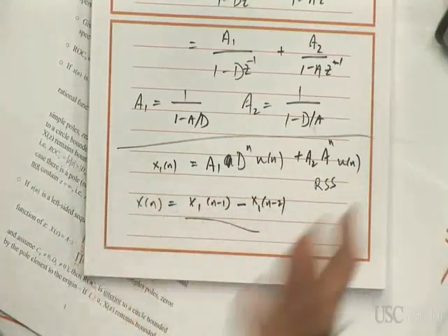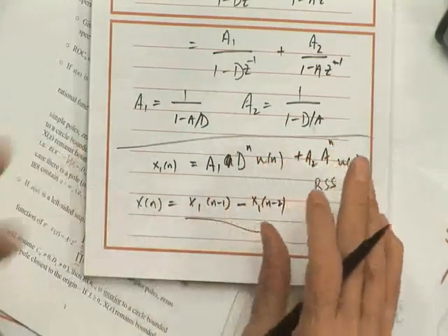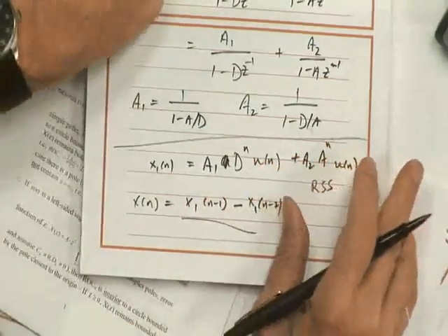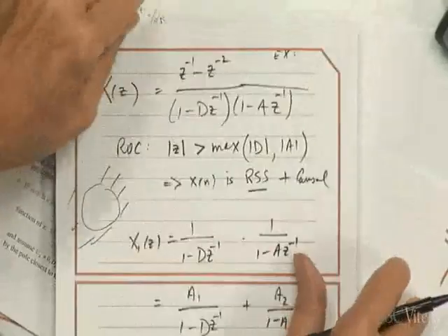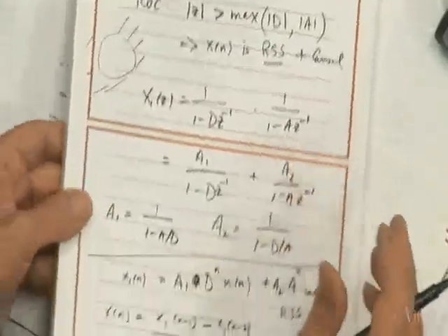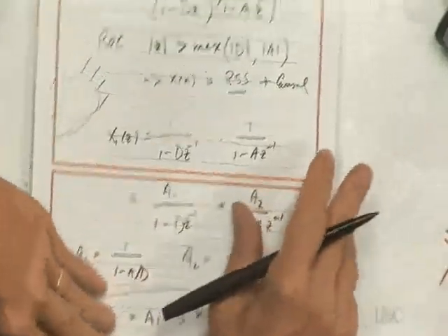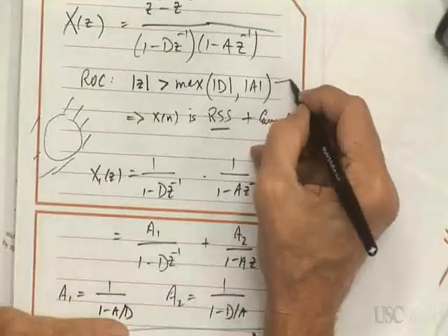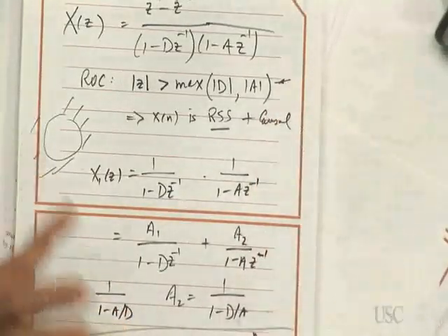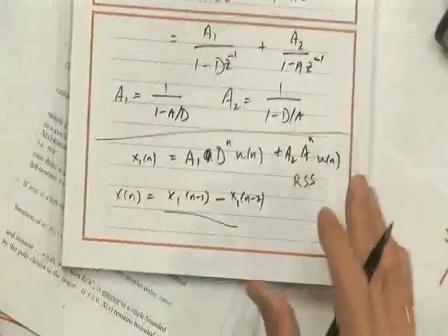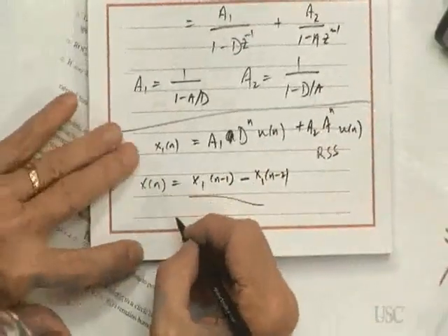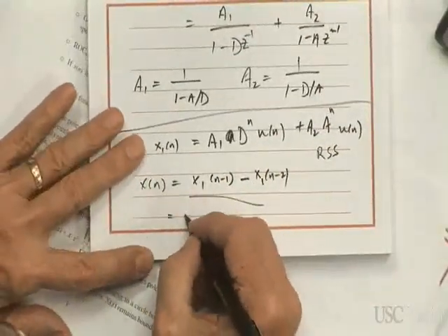So take a look at this example. I find that a nice way of doing inverse Z transforms that have powers in the numerator. It's a simple way to do them. But the key behind this is that I told you what the region of convergence was. And is this causal? You bet.